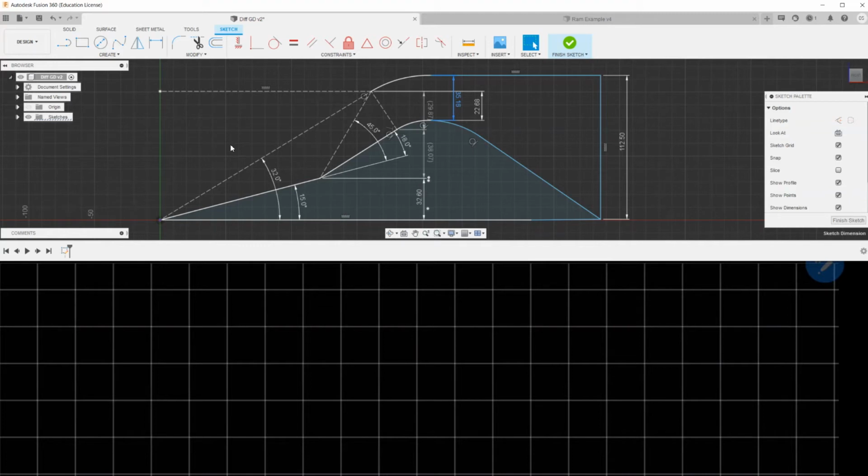In our case, the shock wave and the obstacle are at the same point here, at the start of the body. So flow came here, and at this moment it understands that there is a physical body, so there is no space to turn around or change any flow properties. It just enters the system, and then it flows inside.